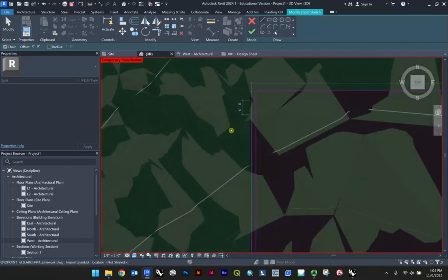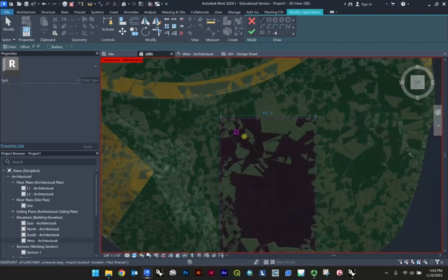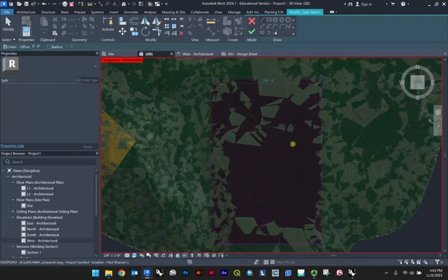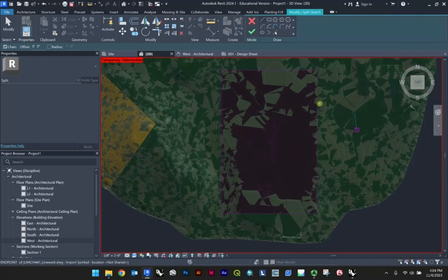And to here. So to get out of this, once you've drawn your box, whatever shape it may be, mine happens to be a rectangle, but just know you can draw additional shapes, and I'll show you how to do that in a second. But hit escape to get out of that command, and you can finish edit mode here.